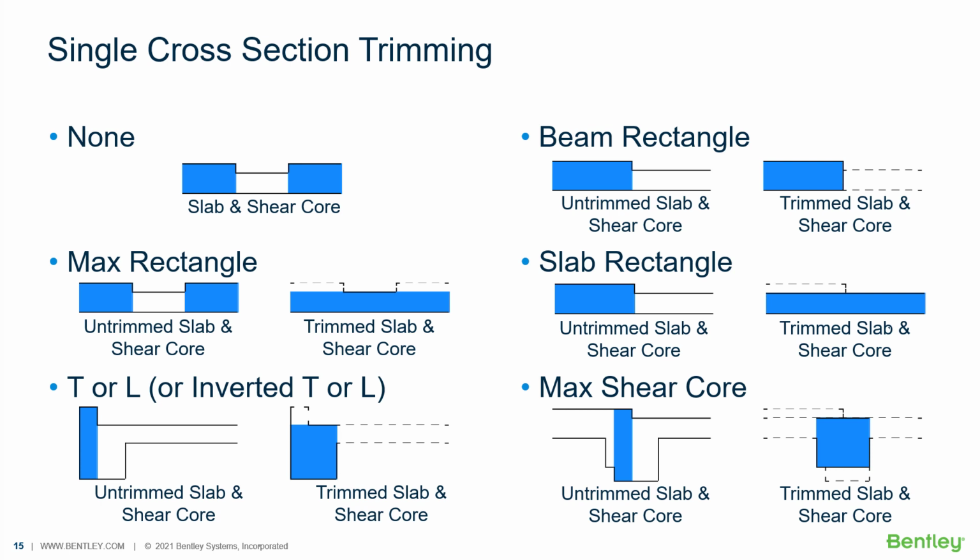What this does is it'll reduce the design strip cross-section based on the geometry, and we have several different options available for this depending upon what your slab configuration is. Now, when I'm thinking about something like a drop panel, I want to think about what types of designs the thickened area of slab should be included for.